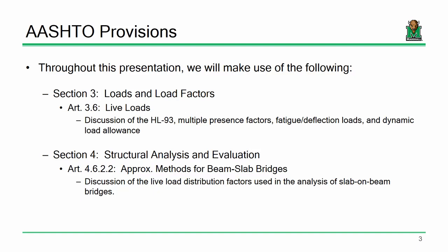There's a lot of three-dimensional characteristics we need to capture with our analysis. Imagine this table is a bridge, and I've got traffic going from one end to the other. I've got this live load placed on the bridge. I have to figure out where to place that live load this way and this way.